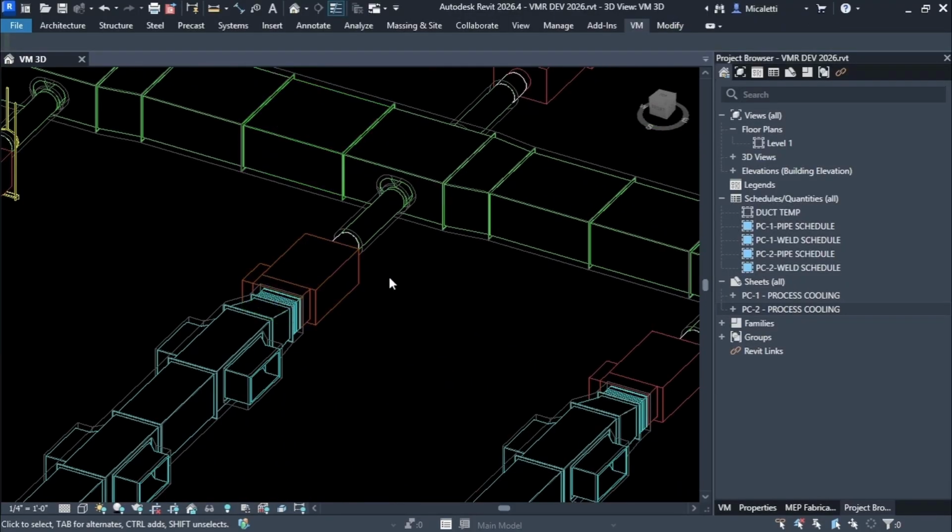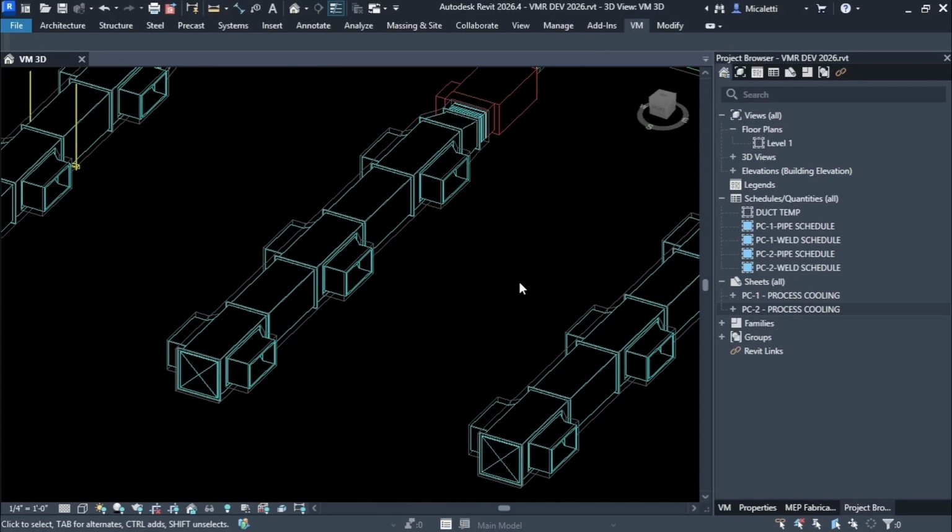It's just a schedule. It's just a schedule, and you're in charge of that. The reason is because there's a million different total stations, and they all take CSV, and every Revit schedule will. So you've got to get with your rep. What order does their total station technology want the points in? And usually it's number, XYZ, and then most of them will allow any other data at the end. They'll ignore it, but you can push it.